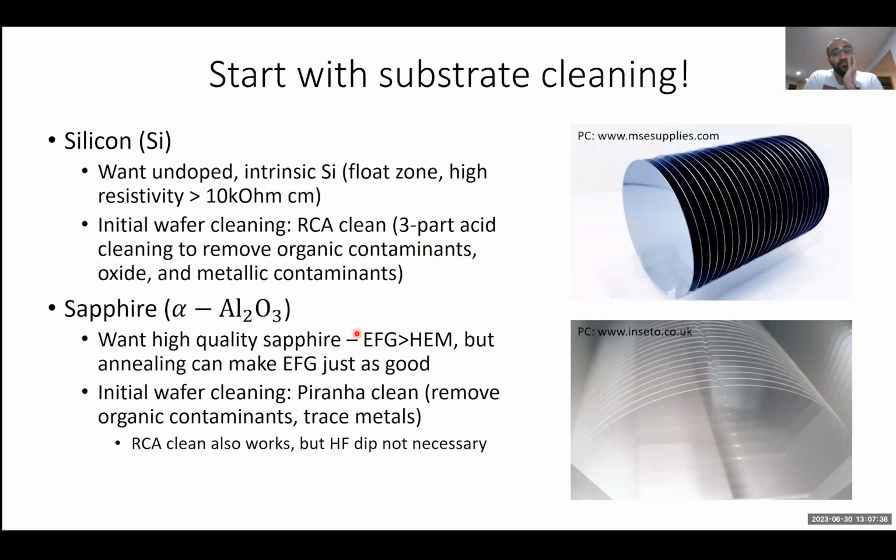Right. So generally, it seems to be the case that silicon with high conductivity or low resistivity ends up being lower loss. You want your substrate to be insulating, ideally, and that will lead to lower dielectric loss, especially in the cryogenic regime.